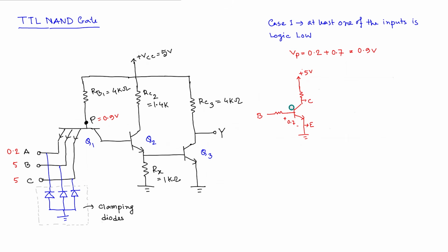So we saw that whenever this voltage drop increases, reducing the collector voltage here, at a certain moment this particular junction also becomes forward biased, so the voltage at this node becomes higher than this, but the voltage required was something like 0.5, if you remember.